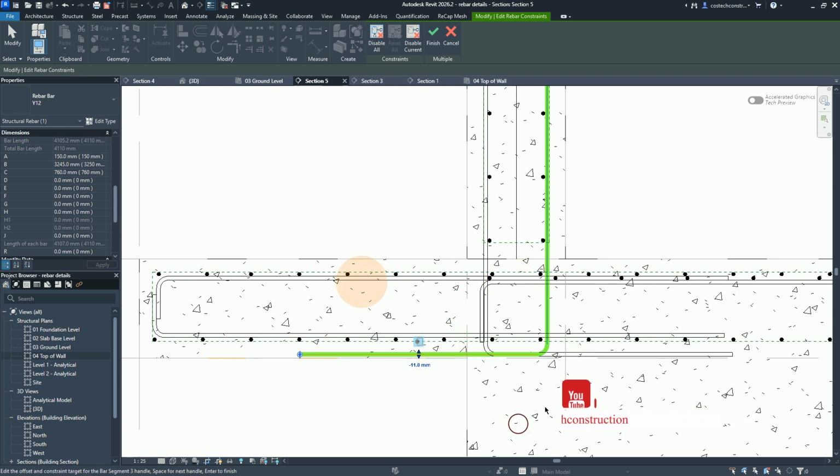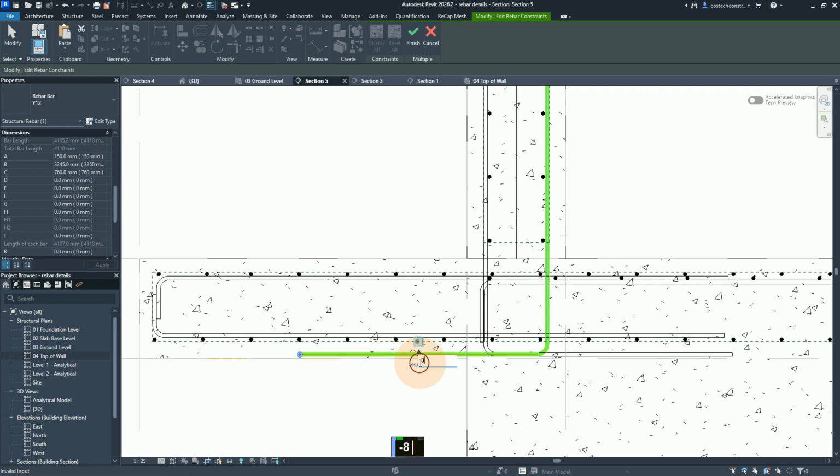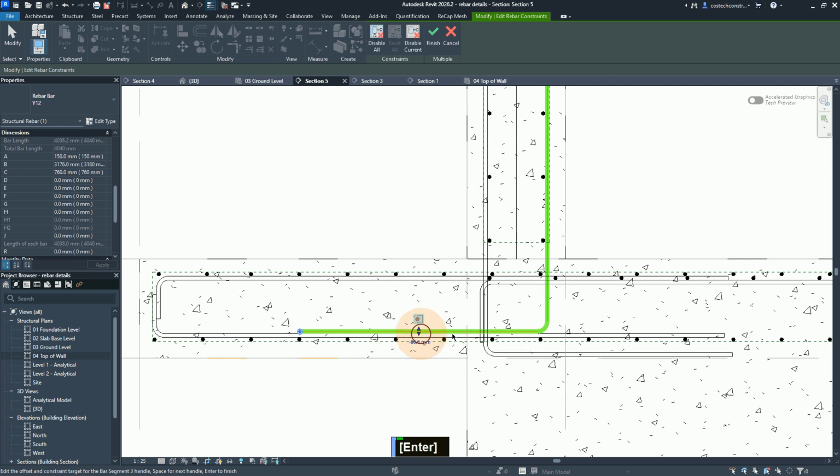But now you detail here that you have changed these details, but you should also have the original one, which has the exact value of B as provided for in the schedule. So for this one, we can modify, and I will modify it. The spacing here, the cover was 50 for the bases plus 24. That will give us 74. So 74 plus half of this diameter, 74 plus 6 will be 80. So I'll come here, then give a value of -80 to bring this up to this point here.